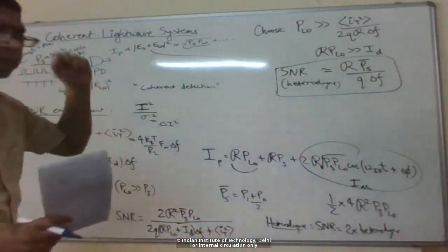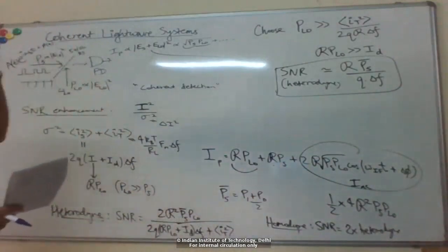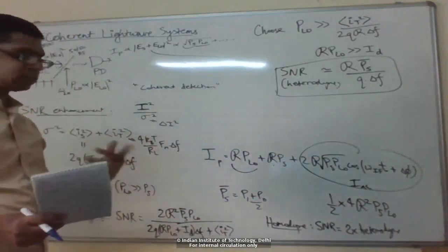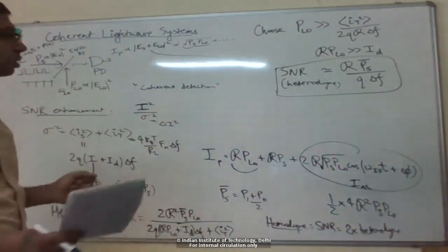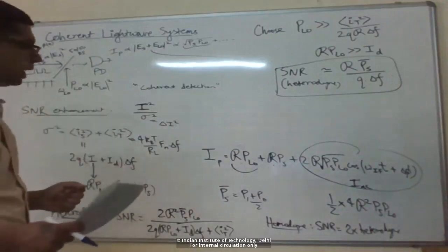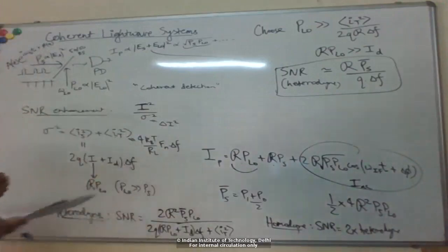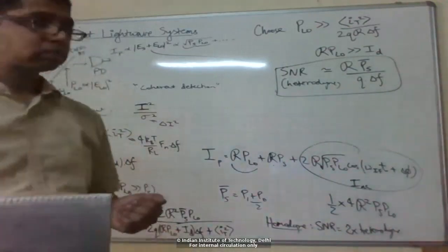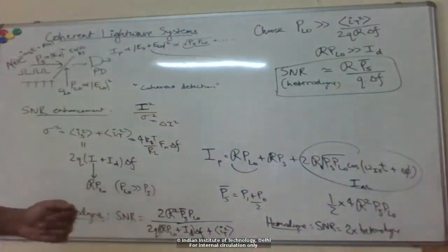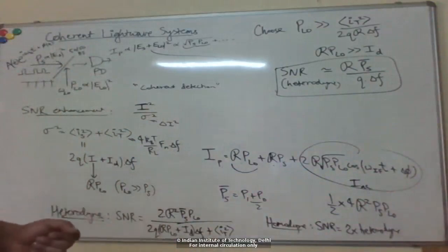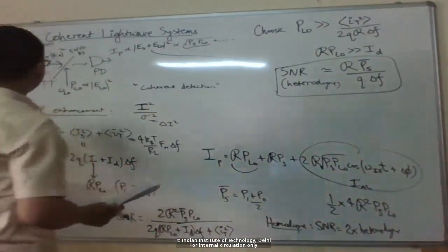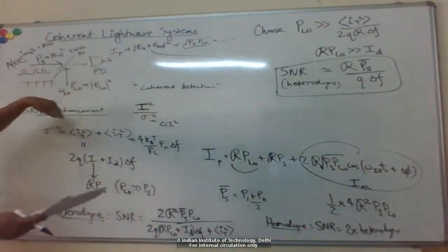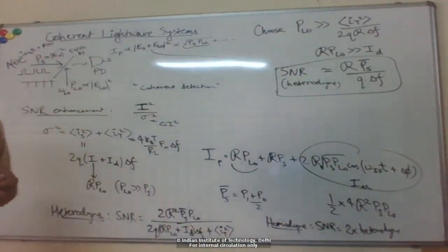photodetector, right? So typically, again, we had discussed that APDs have this electron or avalanche multiplication, which increases the effective gain or responsivity, right? Which lets me go into the shot noise limit. But it, of course, comes with its own problems like excess added noise, etc. But here, even with using a pin photodetector, we can get into the shot noise limit via the local oscillator.